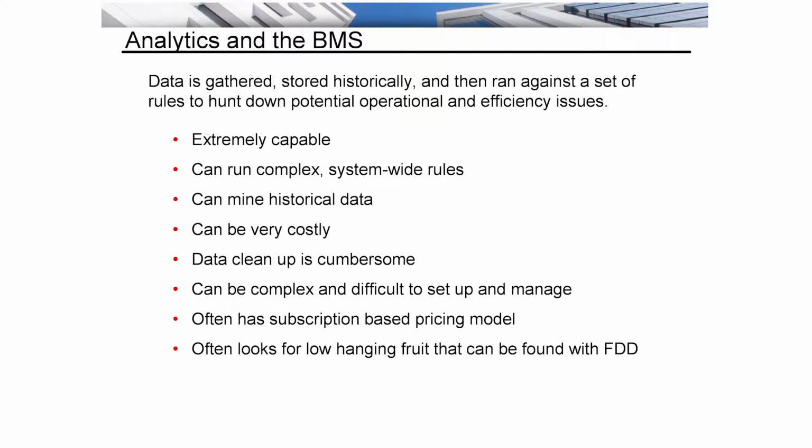So, analytics and the BMS. Data is gathered, stored historically, and then run against a set of rules to hunt down potential operational and efficiency issues. You can run complex system-wide rules. You can mine historical data. Some issues that you do need to be aware of are that the data cleanup can be cumbersome, particularly when you're dealing with older systems. And then you can also have issues with the complexity and difficulty to set up and manage it.